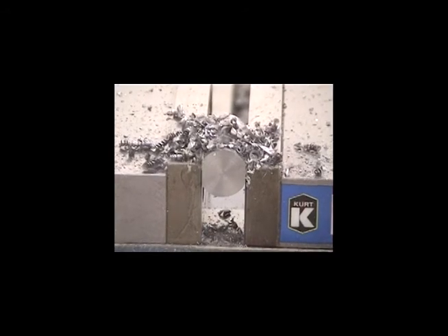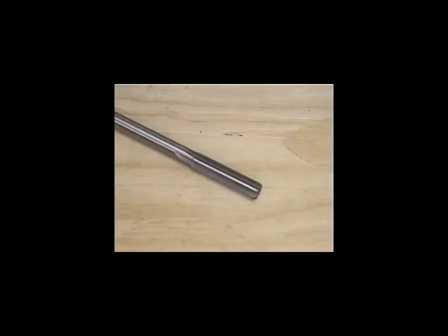Using more bits than the starter bit and the final diameter bit to drill a hole will usually make the hole walls less smooth and make the hole axis less square. Do not use a series of bits to drill and enlarge a hole. On a through hole, always stop before you start drilling into the vise, the table or the spacers. For precision holes, you may want to use a reamer for the final hole diameter. Contact a proctor or watch the lathe video for instructions on reaming a hole.